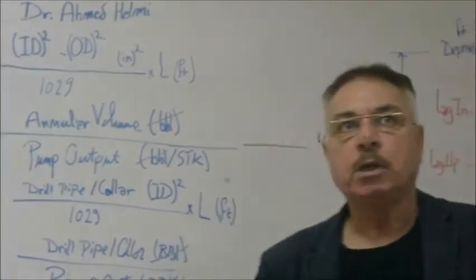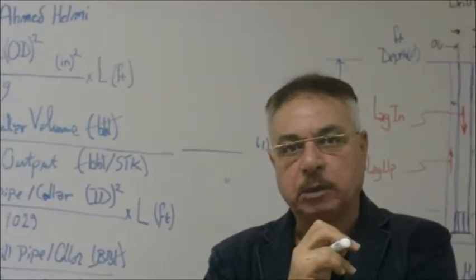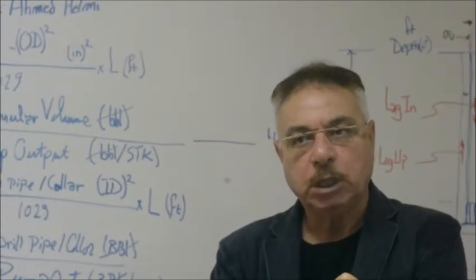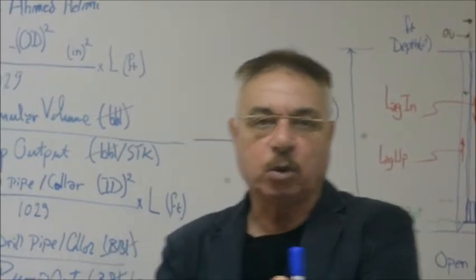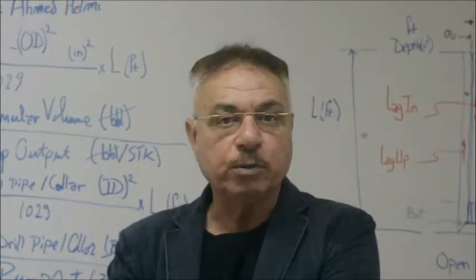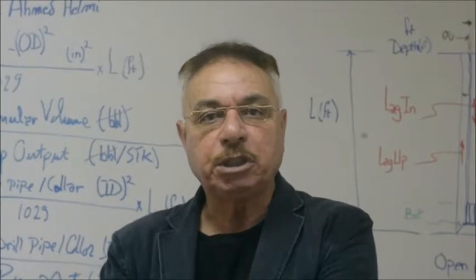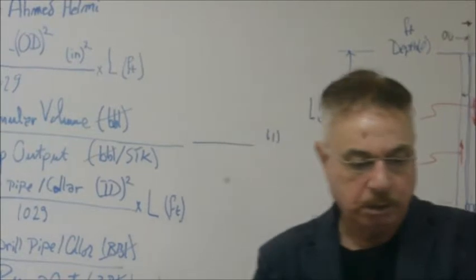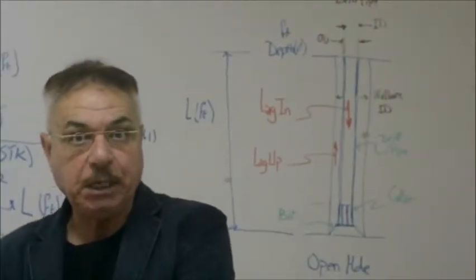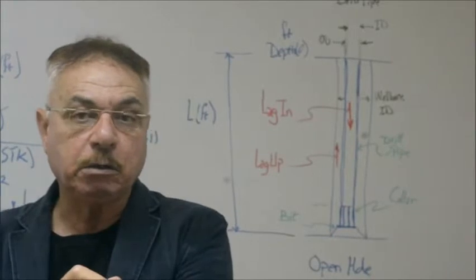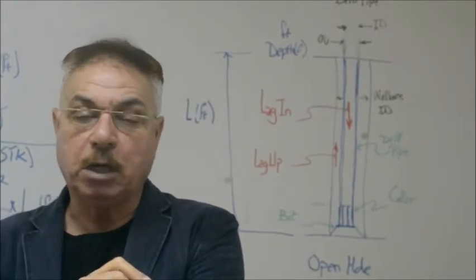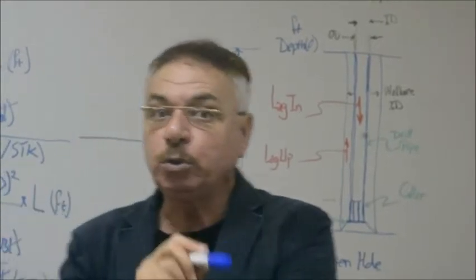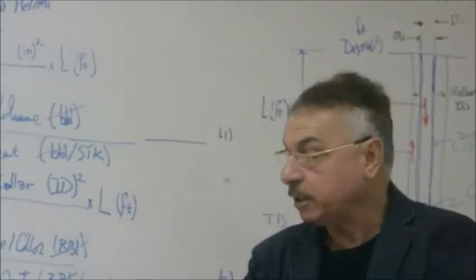And then when calcium carbide is added, it will react with water and acetylene gas is formed. This acetylene gas moves with the mud until it reaches the shale shaker. In the flow line from the BOP to the shale shaker, there is an outlet sampling line that takes the gas coming out with the mud to a gas chromatograph for analysis.